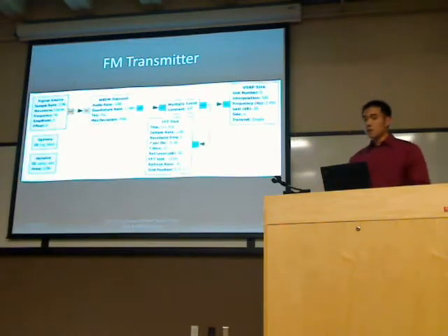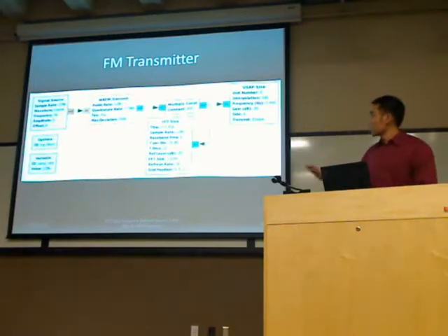And this is just a block in GRC, the signal source input. And what I mentioned earlier, the FM transmitter block, that's the wideband FM that contains the interpolator and pre-emphasis filter as well as the modulation. It goes through, and then it goes to the USRP sink, which connects to the USRP hardware. And I'll explain the reason we chose these specific values later.